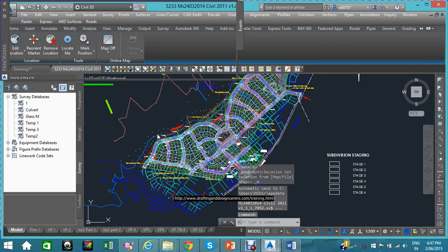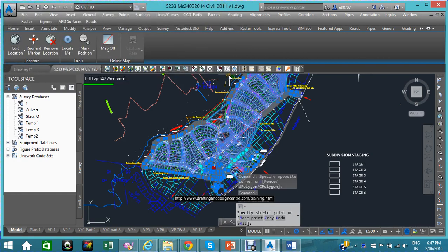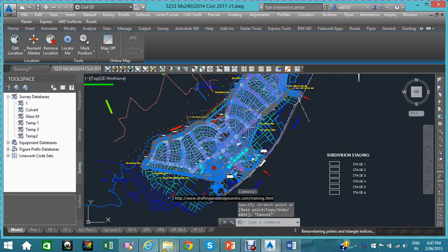Okay, I think my file size is significantly high. Basically, when we drop the image to the Google Earth, we need to make sure that we define 2 points: northing, easting, latitude and longitude, and then we drop the image. So this is a basic functionality in InfraWorks as well as any of the add-on package. Everything is selected right now.